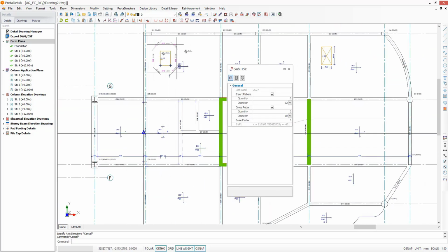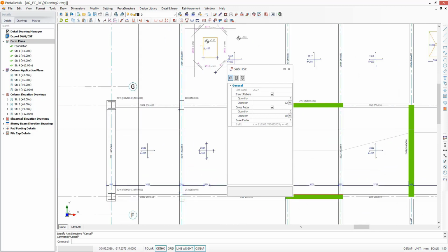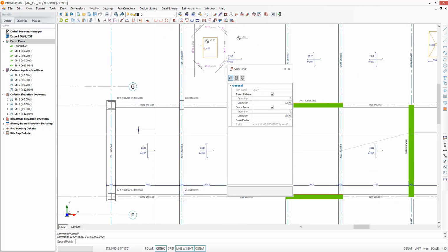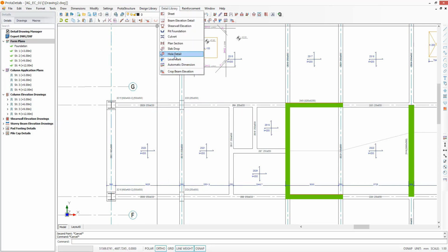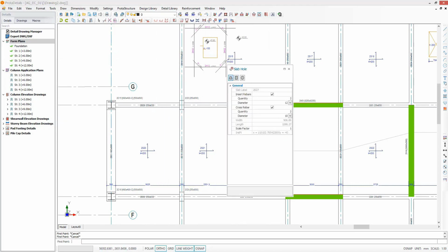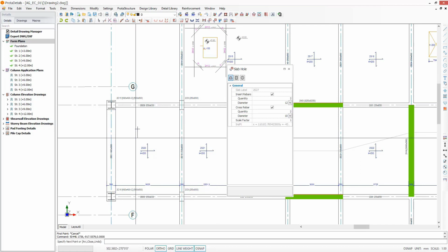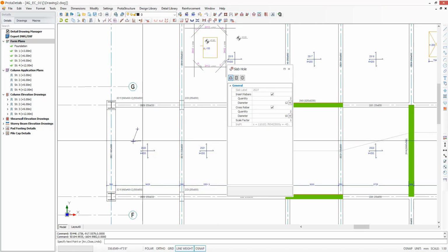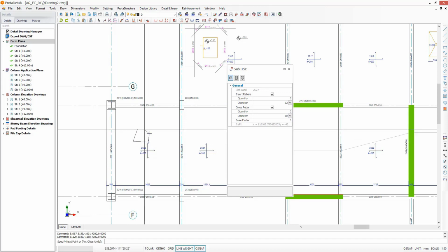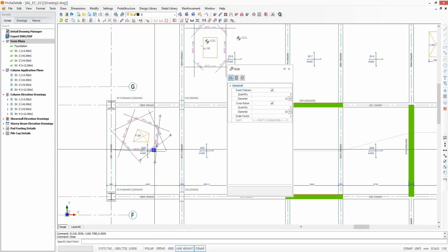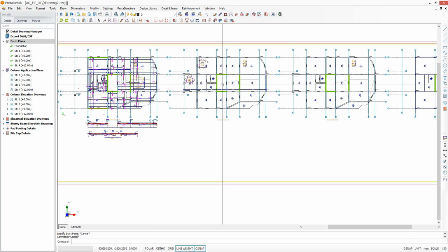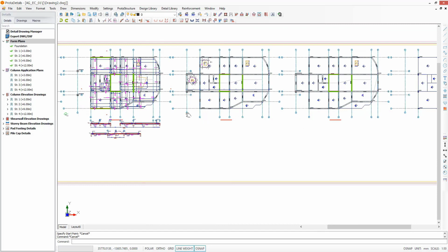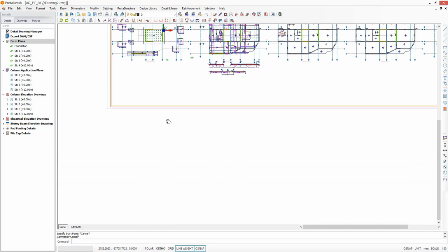Now this time I would like to draw a polygonal hole. Let's draw a polygon. Let's get rid of the ortho. Just close this and it's done. Well, let's see what we can do more with the shear wall elevations and column elevations, since there are a lot of options to apply for them.